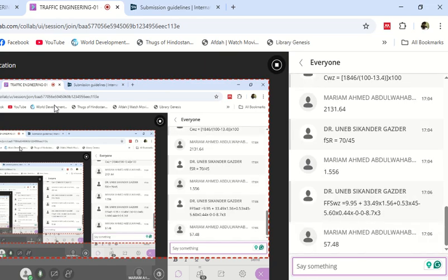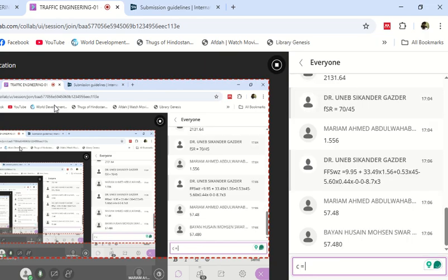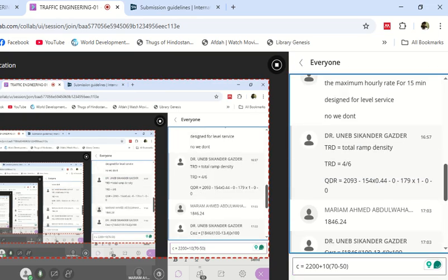Okay, so now we have the free flow speed of the work zone and the capacity of the work zone. If I want the adjustment factors, I need the normal capacity as well. It's a freeway. Normal capacity is for free flow speed, which is 70. Let me just check.